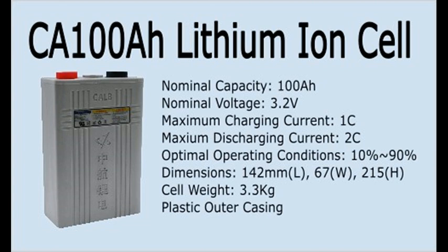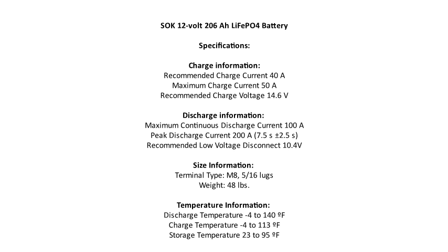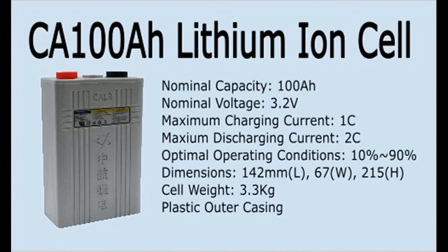You do not want to charge or discharge your battery at a rate that exceeds the battery's capabilities. By checking the specifications of the cells, you'll learn such things as its maximum charge and discharge rates, operating temperature, number of life cycles, and internal resistance, etc. For lithium iron phosphate cells, the charge and discharge rates are usually given as a factor of C. For instance, the continuous discharge rate may be listed as 2C.